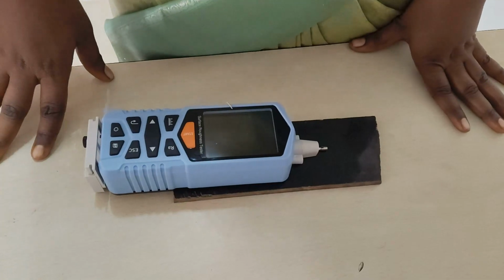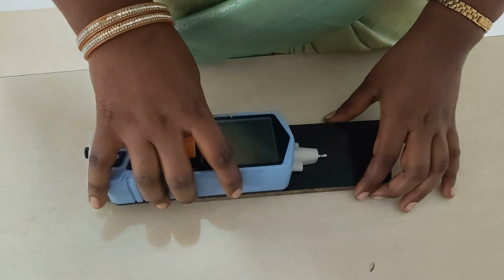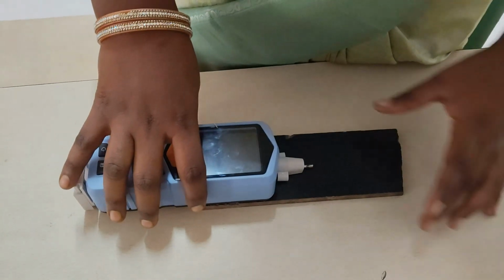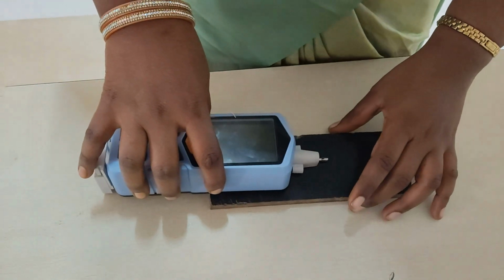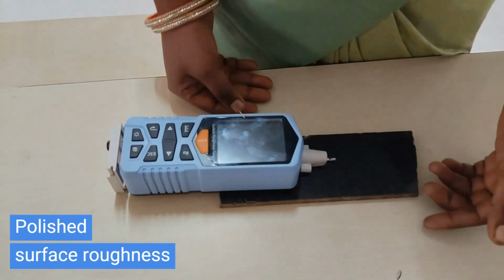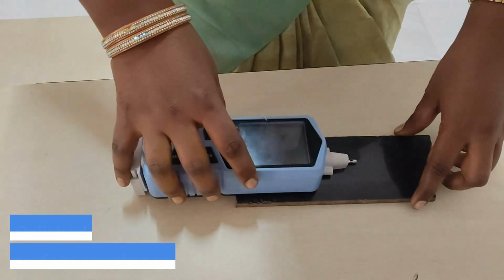The track direction of the pickup must be perpendicular to the direction of the surface structure, or process line, present on the granite stone surface. This is because measuring along the process line may not capture the true surface irregularities.